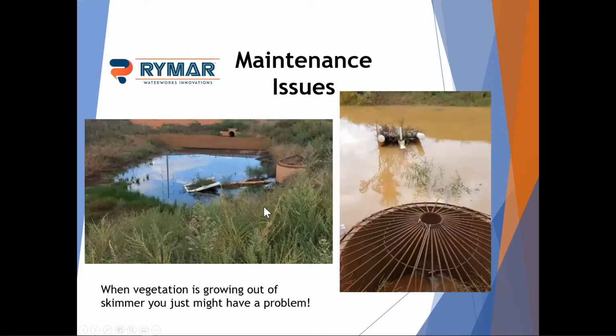And then one other picture, maintenance is required. These are not maintenance free. This particular one actually had a big root ball growing inside of it and was greatly restricting the flow. So, tip of the day, if you see vegetation growing out of the skimmer, you might have a problem, might need to do some maintenance.